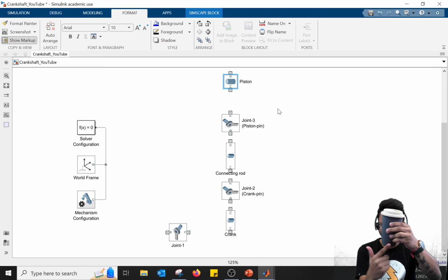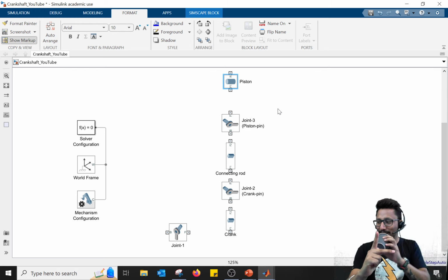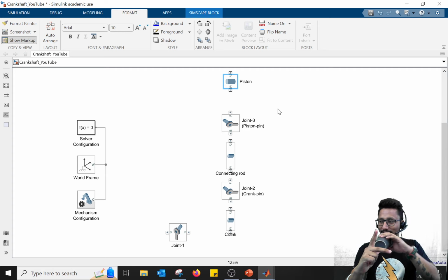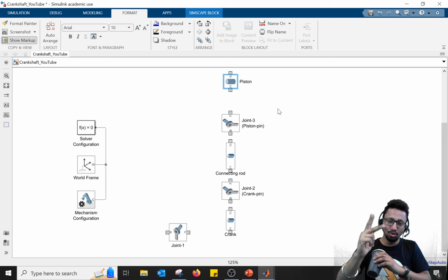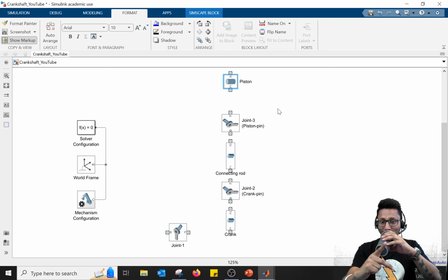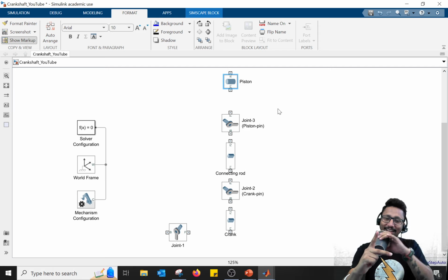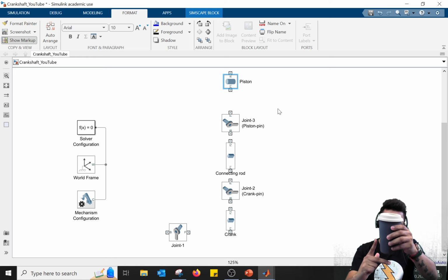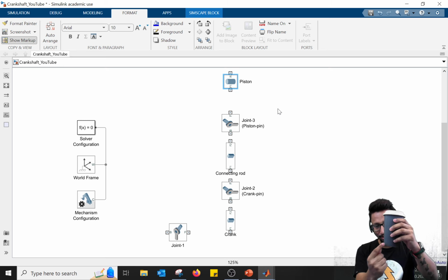This connecting rod. But instead of this motion, it's going to make the piston move like this, because the rotation of this joint 3 is about the z axis. And the moment you connect it with F1, and F1 is at the bottom of this piston, it's also going to rotate like this. We don't want it, right? We want the piston to be like this, such that this joint is here and it's rotating about the z axis.